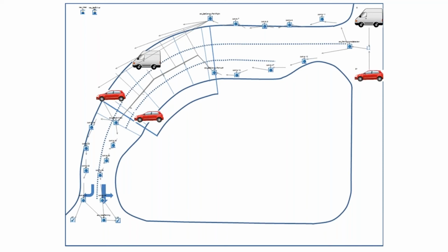And really the question was, okay, do we put that straight to go across the traffic in the right-hand lane or the left-hand lane? Based off of observation data that we had and some of those conversations with our subject matter experts, we were able to model even down to that level of detail. If we put that straight and used a straight-right combination, you're going to have more backing up of traffic because the vast majority of people were trying to turn right, and the fact that they legally can do so, you're really going to back things up, versus there was a lot less traffic turning left to cross traffic or go straight.